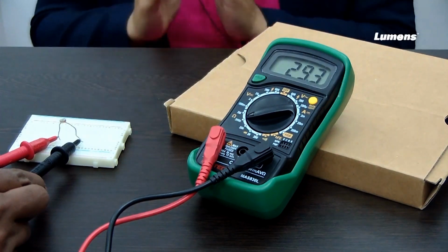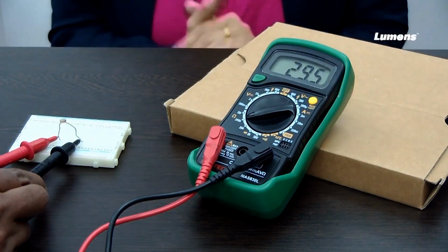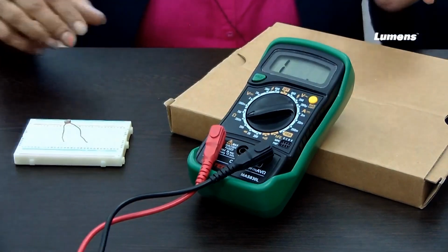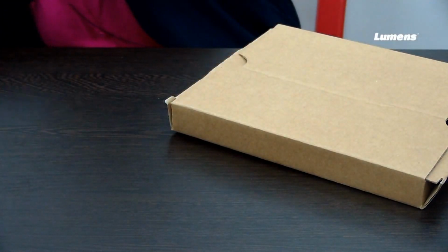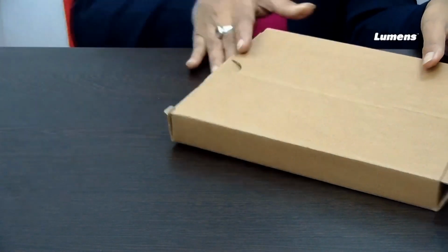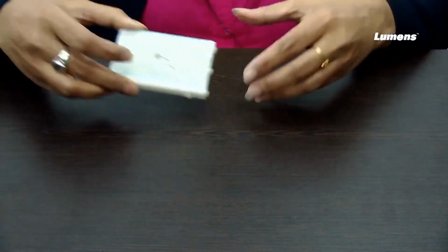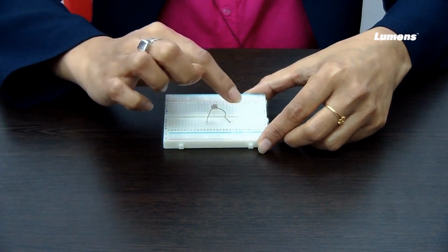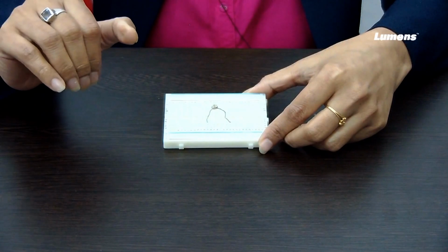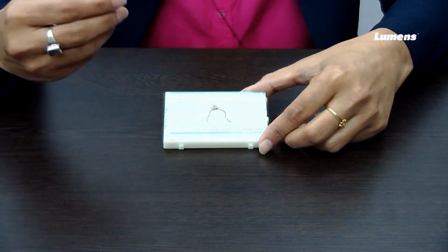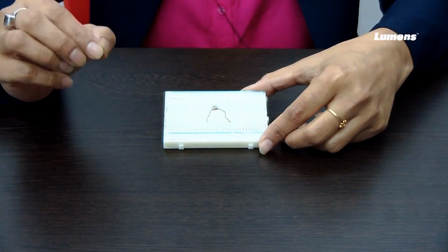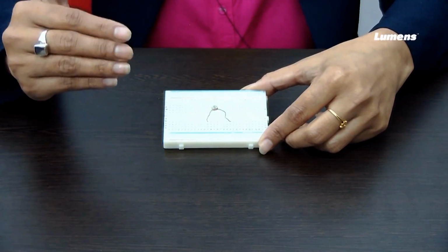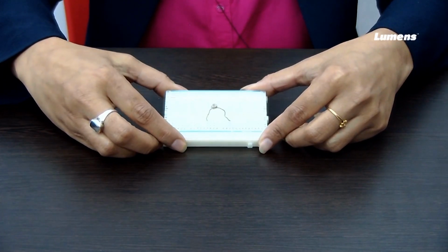Okay. Now, again you see with the full bright light it is coming 29.5. Okay. So, this is a property of this LDR. Okay. So, now I will be showing you the experiment as I said with LDR, but one thing you have to remember, that the value of this particular LDR changes dependent on the ambient light. When you incorporate your code, when you try to design something with LDR, you have to take into consideration these few things. Okay. So, what is the ambient light, and depending on that you have to change your code or anything.